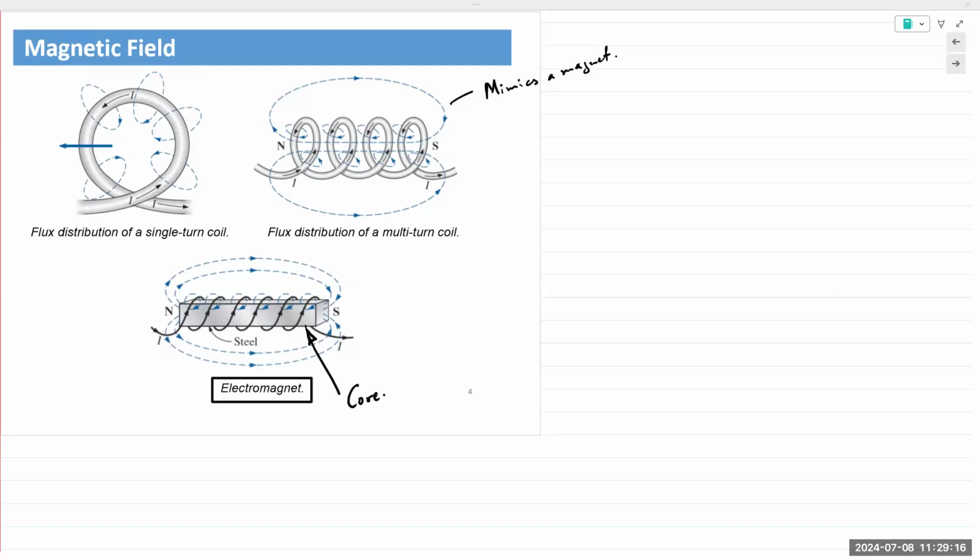The back side of your smart device, whether it's a watch or a smartphone, will have a coil. And when you place it on the wireless charging mat, the coils of both will be interlinked. The electromagnetic field of both coils will become linked, and the charging mat will supply the energy into your smart device through that coil. And the coil inside your smart device will convert that magnetic field energy into electrical energy. There are losses that occur because of this energy transfer taking place, so it gets hot.